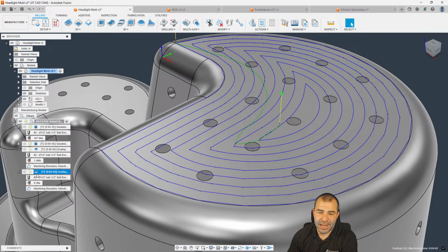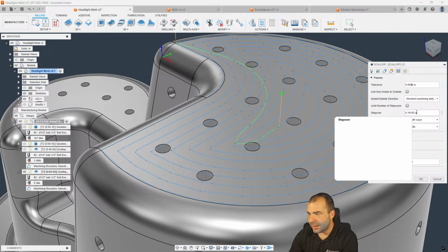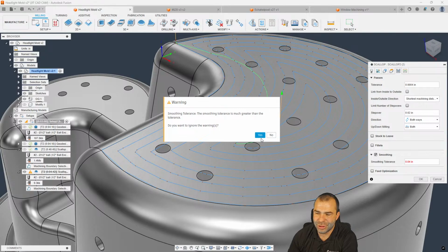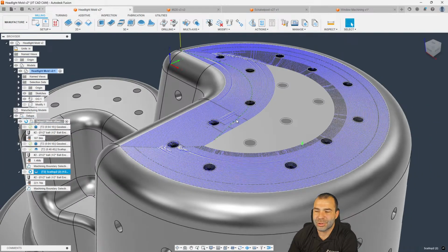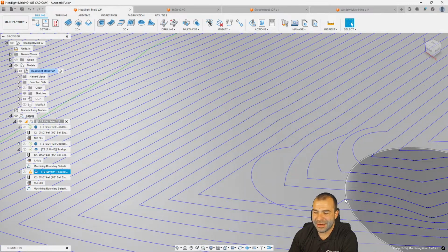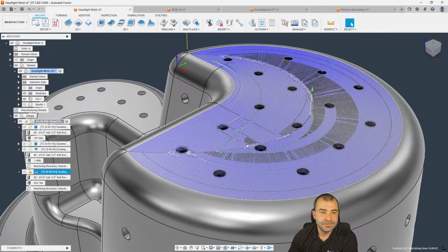Now, you could try to force something where you're like, oh, no, this is going to stay down around 4/10, but this is going to go up to 40, and now I'm going to get an error inside of Fusion. And again, you can start to cause a problem where smoothing has changed from being nice, clean arcs to very, very wild toolpath smoothing type scenarios.